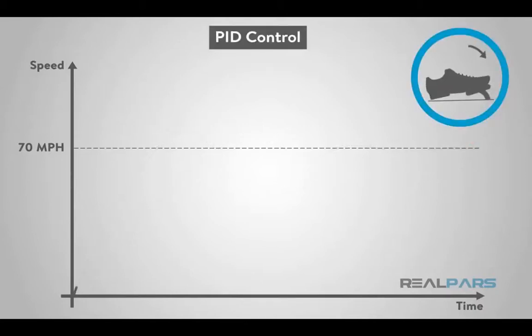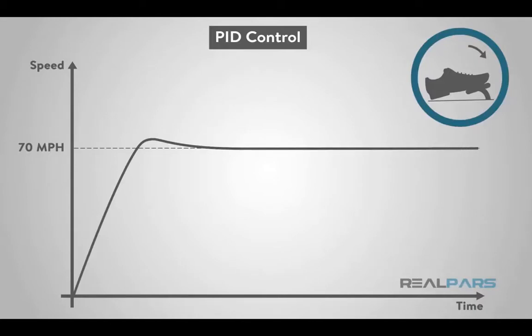And for D, or derivative, you react to sudden changes. Let's say a strong wind gust pushes your car. Suddenly your speed surges fast upward toward the desired speed. You become startled, so you release the gas pedal. As the speed surge ends and the speed stabilizes, you will then return the pedal to where it was. Derivative control manages sudden surges and may prevent overshooting your target speed.